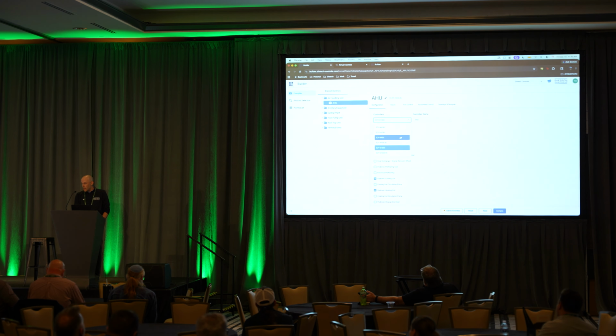So it's as easy as going through BI, checking a box for equipment type, air handler. We do have ASHRAE Guideline 36 compliance in here, so determine response logic. We have a specific section on the GFX program that is auto-populated. It's actually a great tool to show you how we pass data back and forth effectively. So even if you're not using Guideline 36, it's a good template to show you how to pass data across networks. So we can click Guideline 36, choose multiple zones.